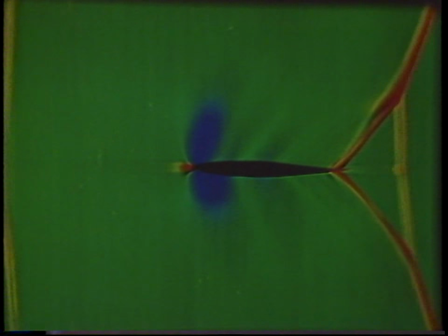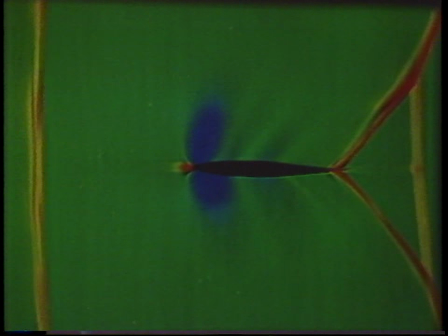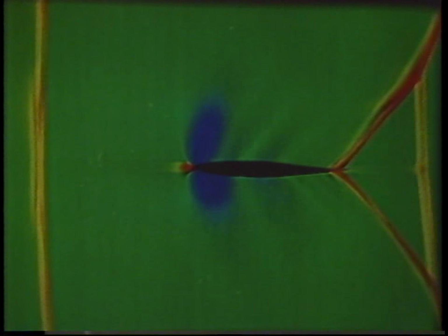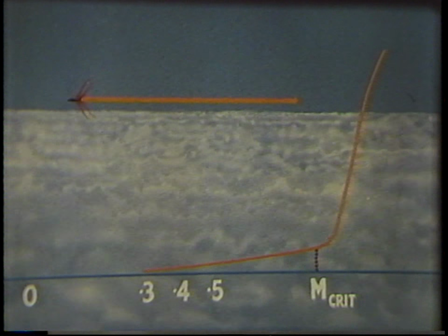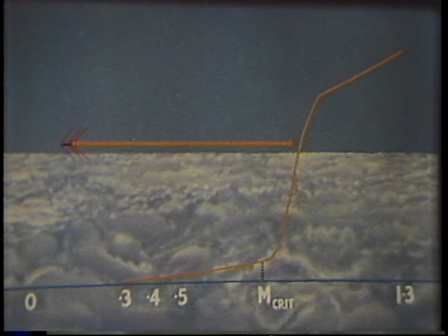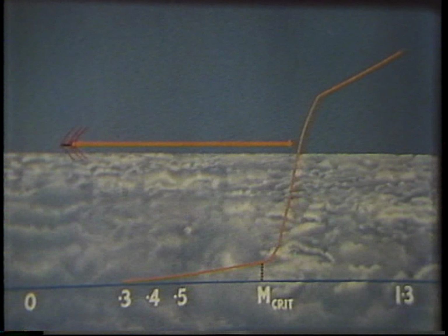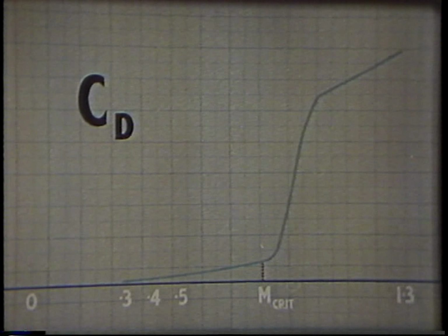Above Mach 1, the wing shocks have reached the trailing edge and now grow much more slowly. The wave drag of the bow wave also changes, but gradually. So the drag rise becomes less steep again towards the upper end of the transonic range. These changes in drag can be seen more clearly in the behavior of the drag coefficient.